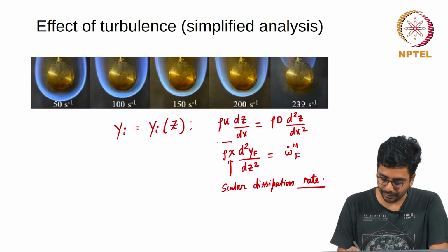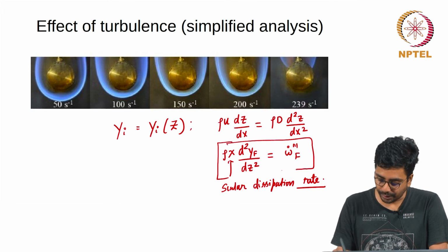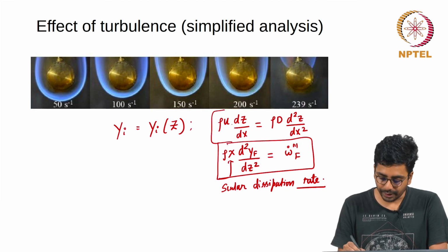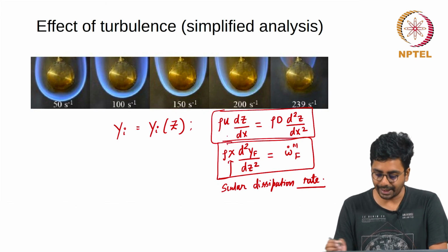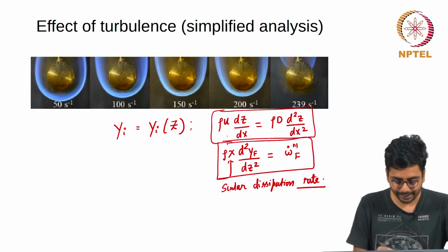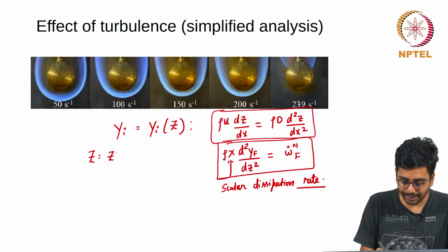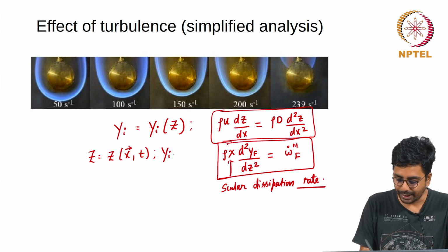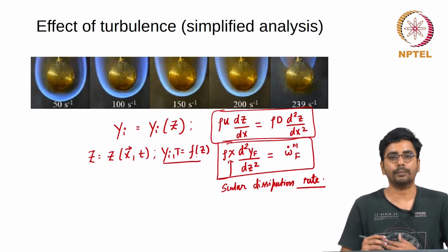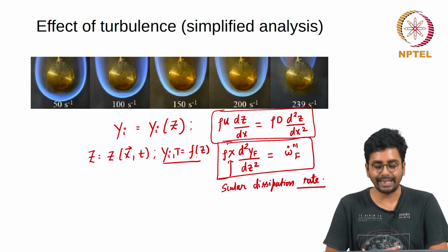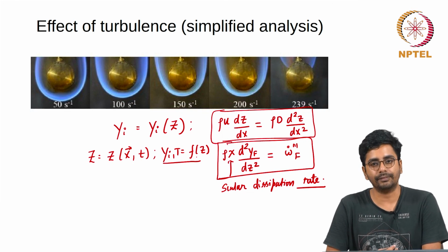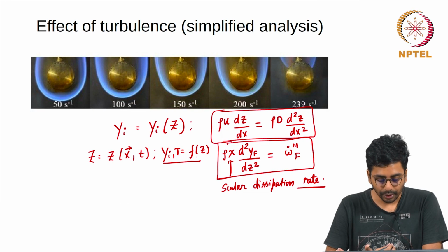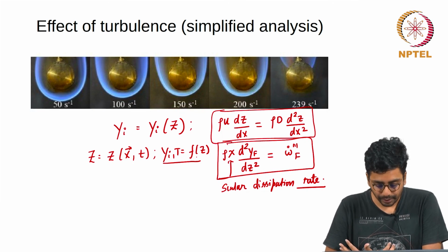So, the internal structure of the flame is a solution to this equation, and for the turbulent flow part we can get z as a function of time and x. We already know Y, I and T as a function of z, and using appropriate statistical methods we can describe a turbulent non-premixed flame as an ensemble of laminar flamelets.